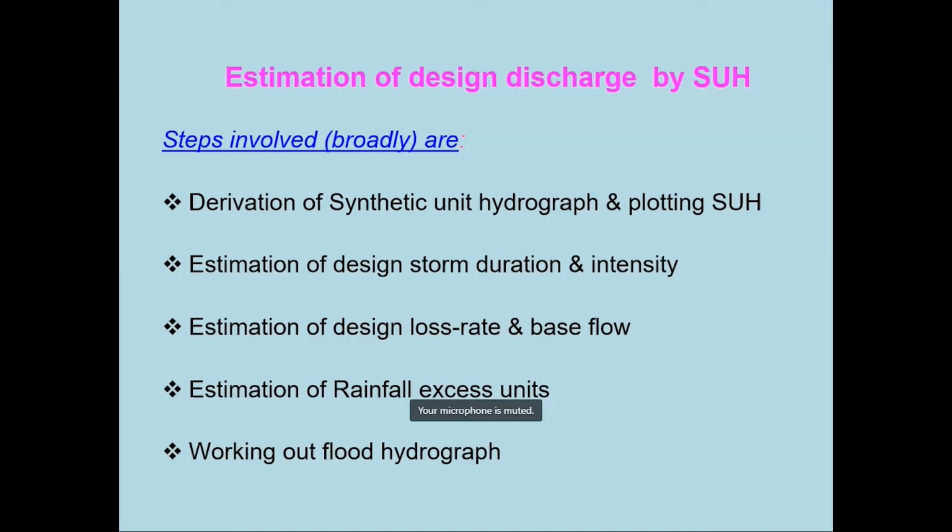If the Ganga is lower than its danger level, but the Gandak is higher than its danger level and contributing much water, then the lower level of Ganga added to the higher level of Gandak can cause difficulty. That is why the final hydrograph is necessary for the analysis of the rivers downstream. Otherwise, the maximum discharge coming for the Ganga is good enough for deciding the bridge on river Ganga.